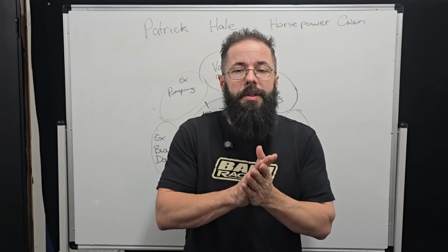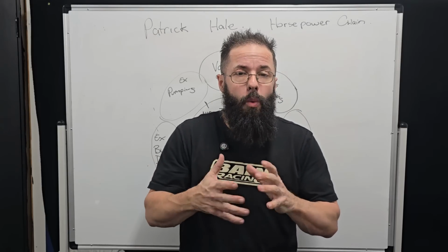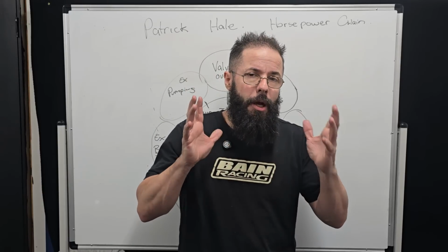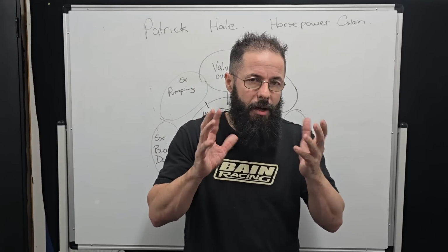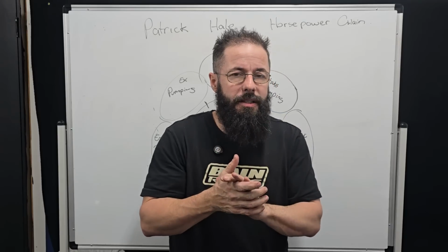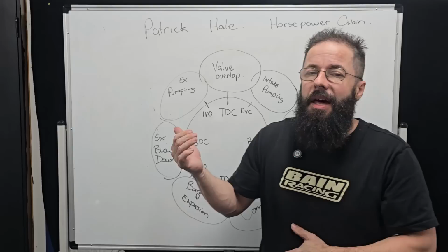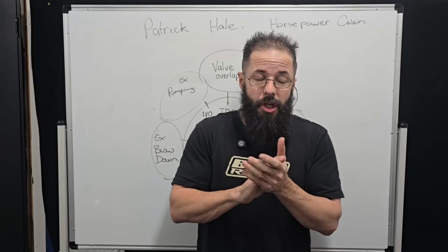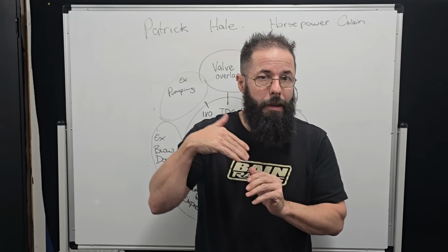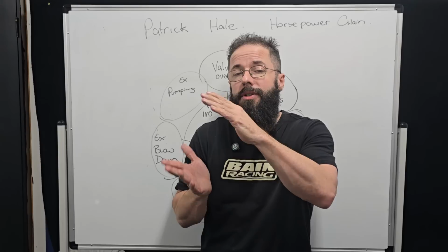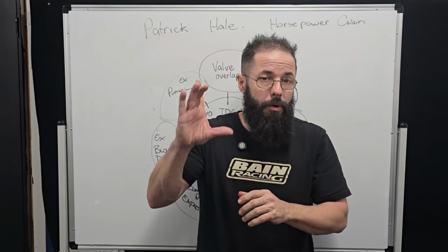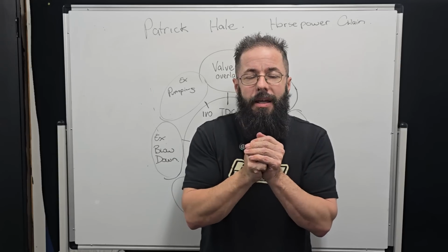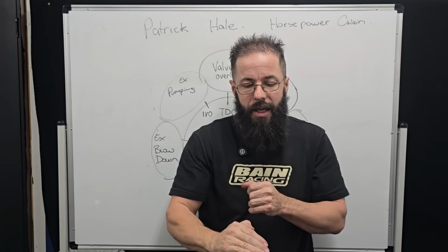It'll make more sense when we start looking at the actual wave harmonics or pressure and velocity, but this will help you understand the complexity behind a camshaft and how it actually relates, especially with the blowdown event. And Darren's talked about this a lot, and a lot of people don't realize it. Generally, most engines by mid-bore, you're blowing off that power. You're really only using about 30 to 40 degrees of the top cylinder to use the force. And because we also need to remember that the piston doesn't go down the bore evenly.